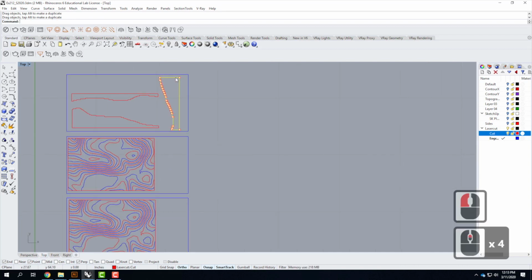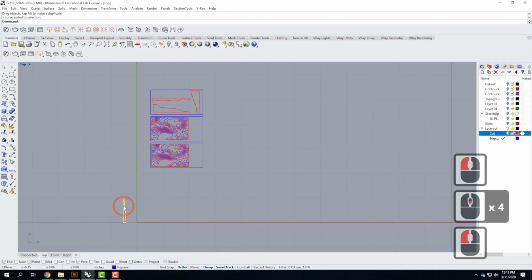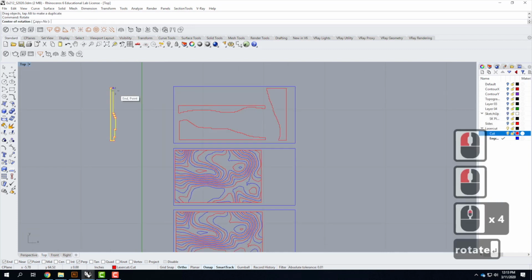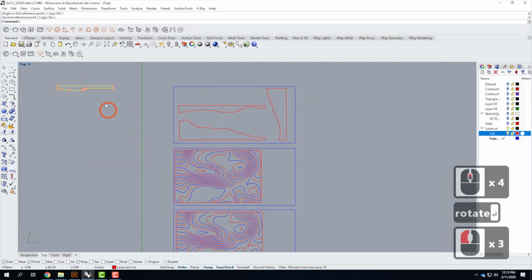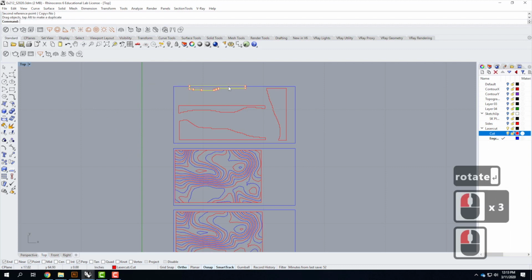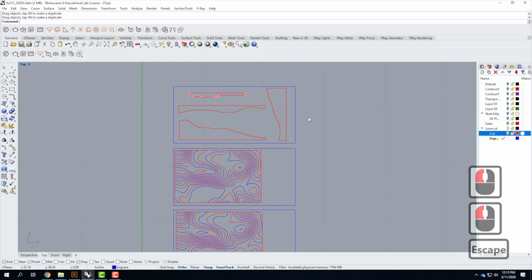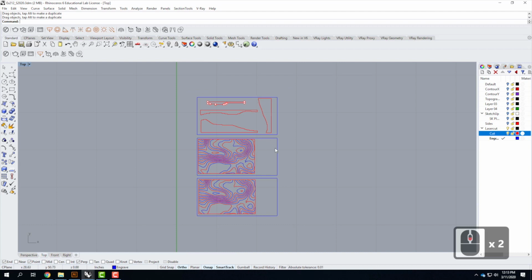So for example, if I wanted this one to be cut on this sheet, I could rotate it, and then I could move it here, which is perfectly fine. The key is not to mirror them. As long as we're rotating and keeping flat, we'll still know how to fold them back up. Alternatively, I could have put them at the end of these 2 sheets, but I still need the larger sheet to be able to cut these.